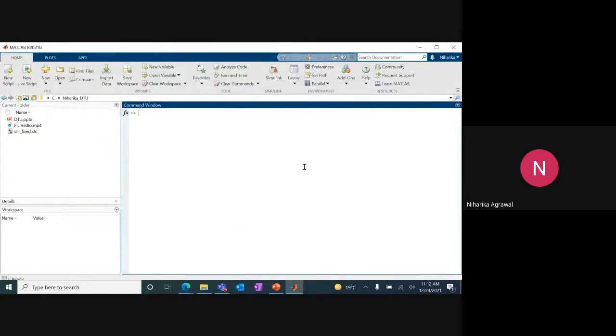But before going deep into the hardware support packages and hardware, I would just like to tell you how we can generate the VHDL code in just seconds. For that, you just need MATLAB software. I'm going to show you a very basic example of a fixed coefficient FIR filter, which is a shipping example. You can easily implement it in your MATLAB window also. For that, I will type sfir_fixed and press enter.